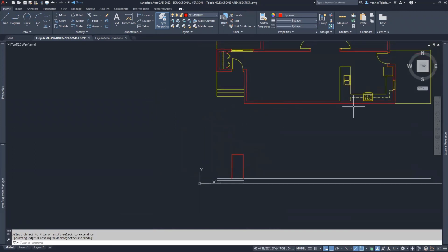This part of the wall is really what's in the foreground. So I should probably draw the lines that represent that right now. And those will go on this heavy layer because that's in the foreground. So I'm going to type L, enter, and from this point straight down.